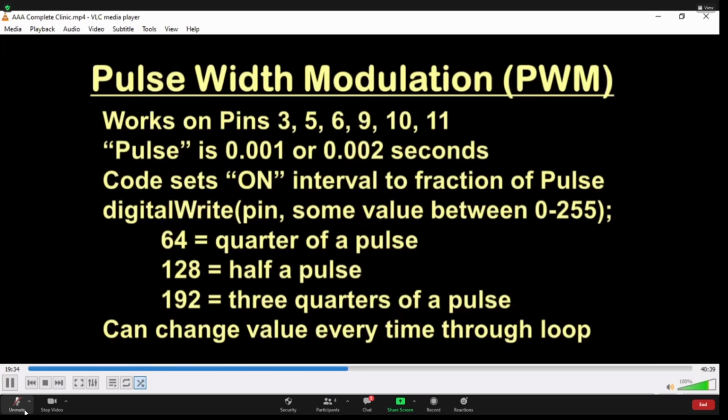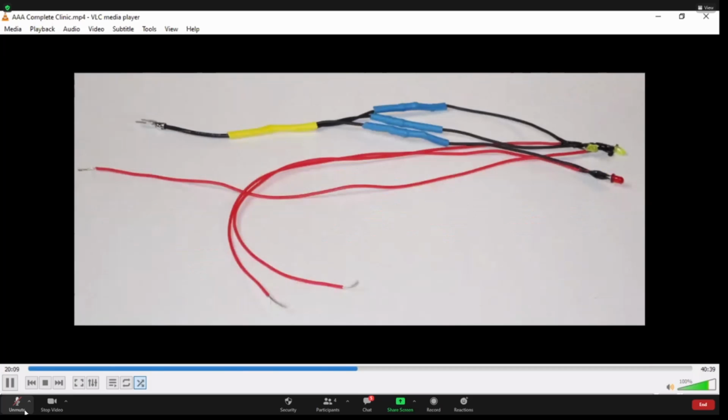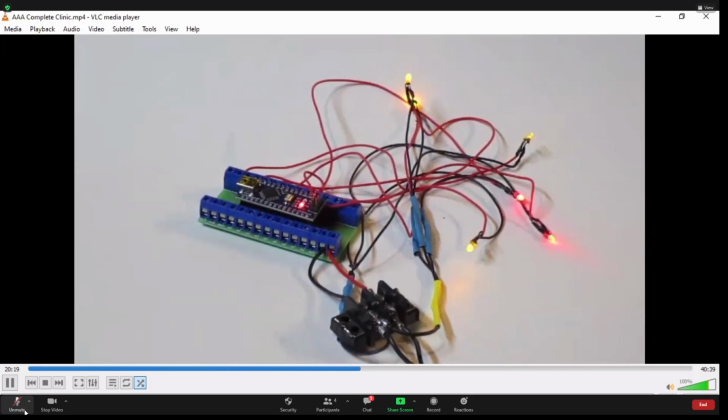I didn't want to solder spade connectors to 6 ground wires, so instead I bundled 3 together at a time and soldered a pigtail to the bundle, insulating the joint with heat shrink tubing, and soldered a spade connector to the free end of the pigtail. I connected the spade connectors to the ground position of the barrier strip. You did use black colored wire for your LED ground wires, didn't you? And then connected the red LED wires into the expansion board positions listed above.